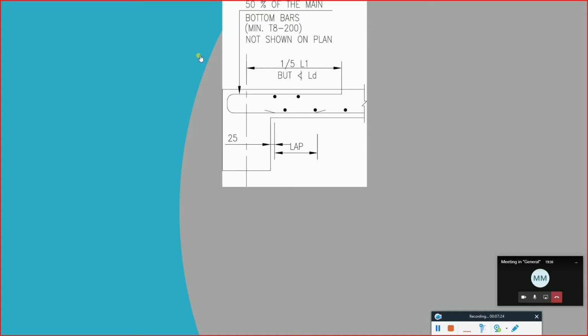Now, in case of a simply supported slab, it goes from zero and then a parabolic curve to zero once again. It means that all the reinforcement is at the bottom, since there is no negative bending moment. Now in this case, even if there is no negative bending moment, we need reinforcement for the connection between the slab and the beam, whether it's simply supported or a discontinuous case.